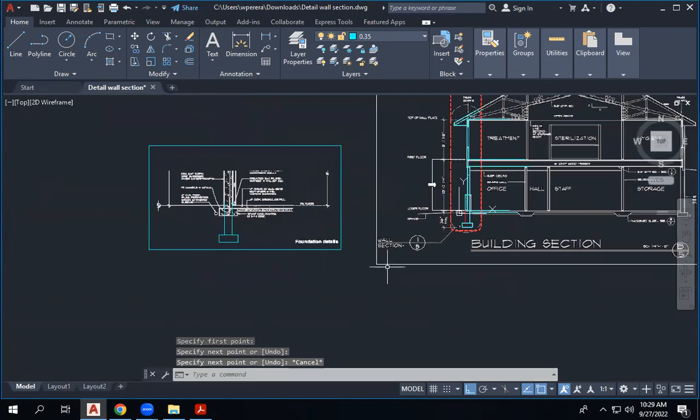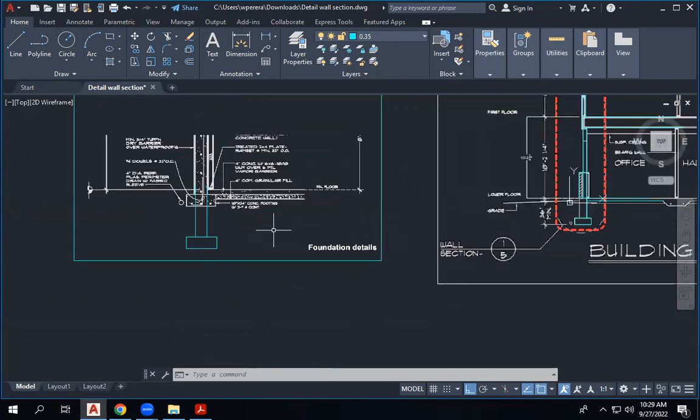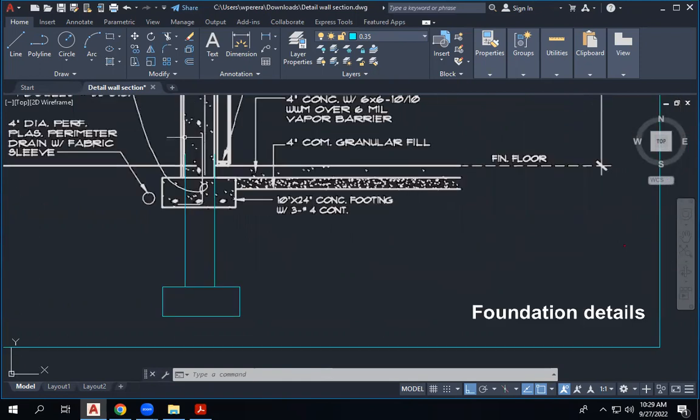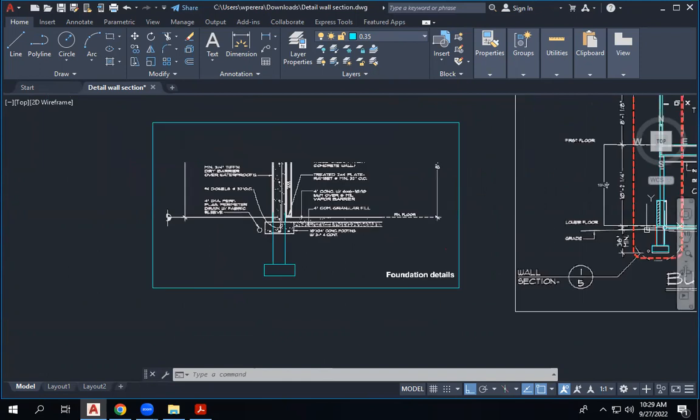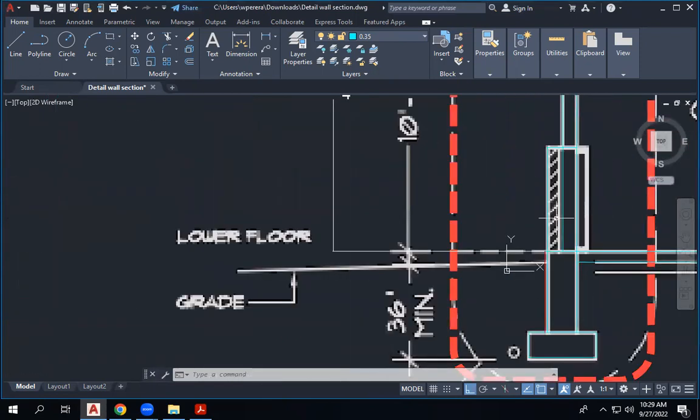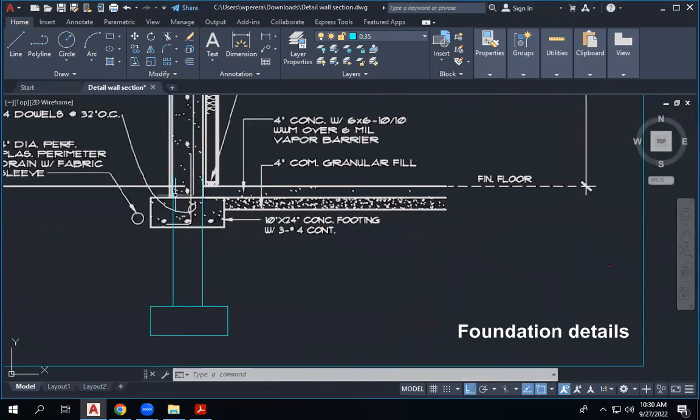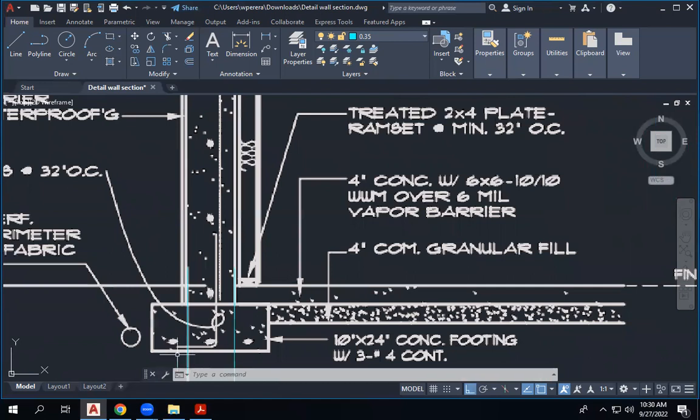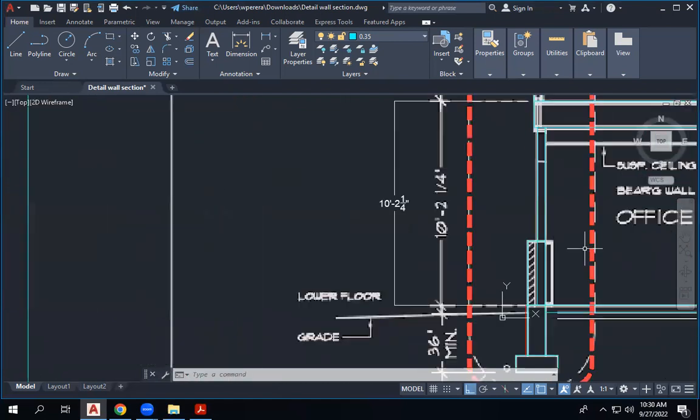You see now that both are almost the same. So that's what we did, we put the footing. This vapor barrier we have has gone all the way right up to the top. So what we do is we will have it right up to this point, and this will be the concrete. It shows the whole thing as the concrete, so you can take up to this point.